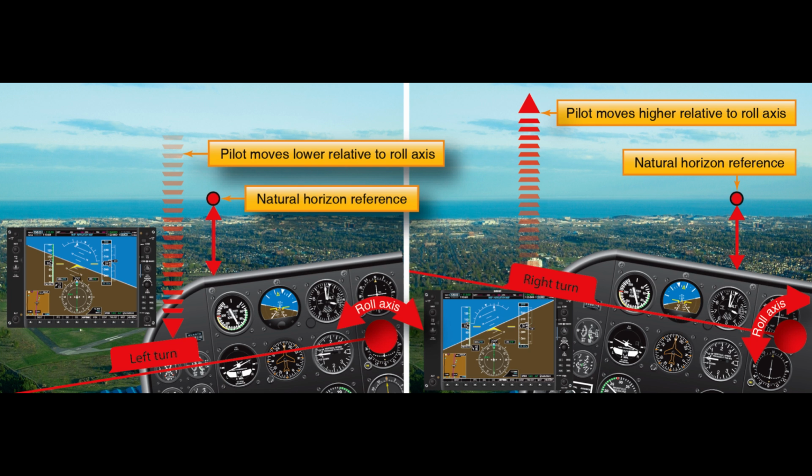Climbs and climbing turns. When an airplane enters a climb, excess lift needs to be developed to overcome the weight or gravity. This requirement to develop more lift results in more induced drag, which either results in decreased airspeed or an increased power setting to maintain a minimum airspeed in the climb. An airplane can only sustain a climb when there is sufficient thrust to offset increased drag, therefore, climb rate is limited by the excess thrust available.